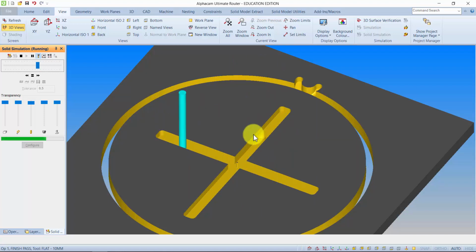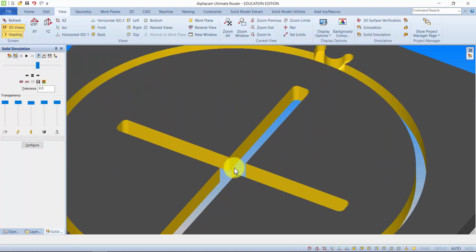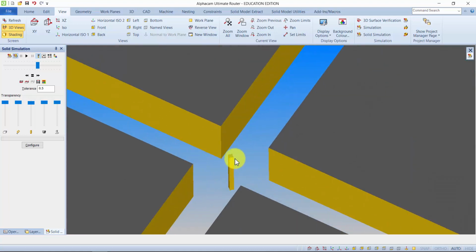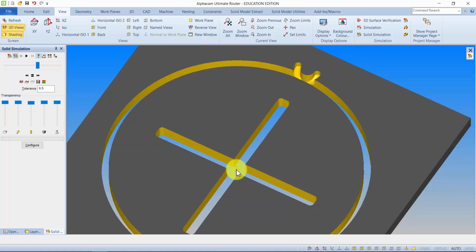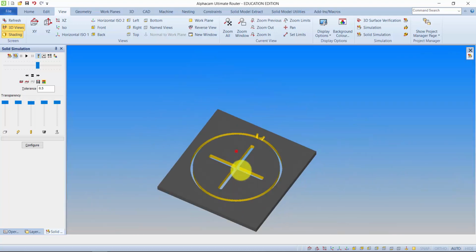And you can see, because of the size of the tool, it leaves this small little island, this small piece of material in the middle there, and I certainly don't think that's big enough to cause any hassle. That would just fall away. If that was a larger piece that was going to come clear, I might use a larger tool in the center or use a technique called pocketing, which we'll get to, to actually remove that. But so far so good, that looks good.